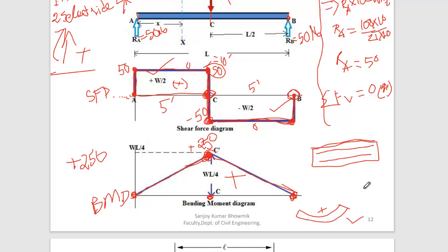Yes, sir. Now, can you tell me which rod will resist this positive bending? Upper layer rod or bottom layer rod? Bottom. Very good. So that means what? Why do you place the bottom layer rod, or where do we put the bottom layer rod? That means where we have the positive moment, right? So technically, in the position where we do not have the negative moment, vice versa, you can also learn this situation.